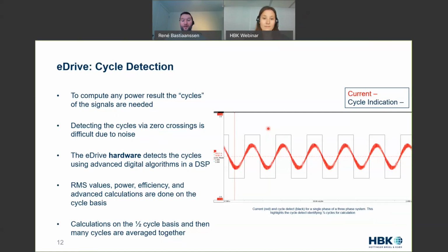So we can either take the dynamic signal, which is one single measurement, or we can take the statistically improved result, which is the average of multiple. But then you lose some of your dynamics. Good thing is the system, having its DSPs, is capable of doing both. So we can give results with a high bandwidth, with the update rate of 1/2 cycle, while at the same time calculating a sliding average of a multitude of cycles. I hope that explains the question a bit.